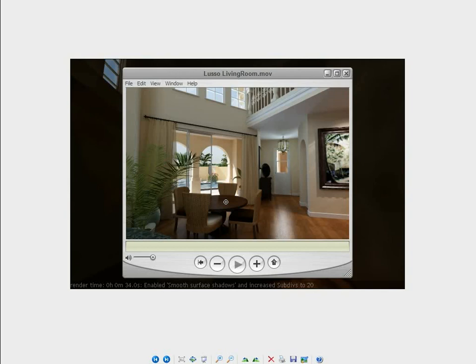Even if an object like a chair is just a few inches away from the window or door opening, but it's so close that it actually occupies the same space as the light, I would still want to place the light just outside, because you can easily have an unrealistic hotspot appear in your objects that are very close to the light. But with the exception of objects that are just in front of the window or door opening, I will always want to place the light just inside.